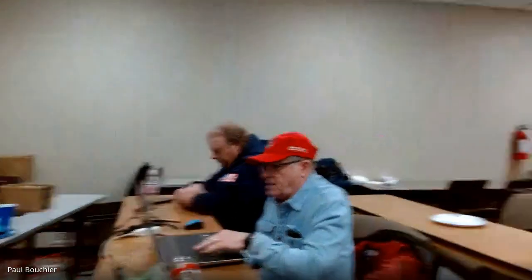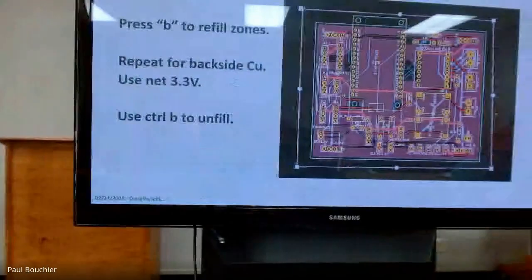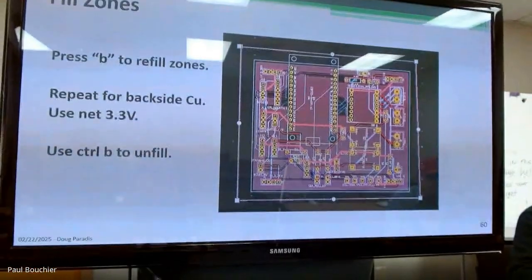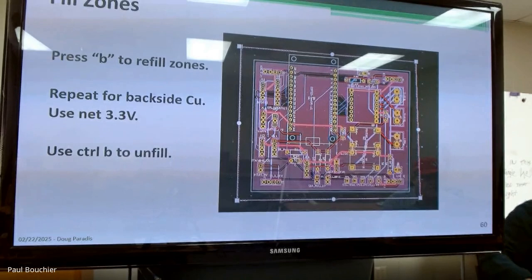By the way, I have an answer to how to see the PCB from the backside without doing the 3D view. Select it all and hit the F button for flip. If you do Control A, F, it flips back. You flip the board: Control A to select everything and then hit F. Okay, I like it.